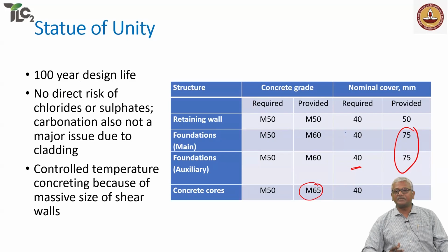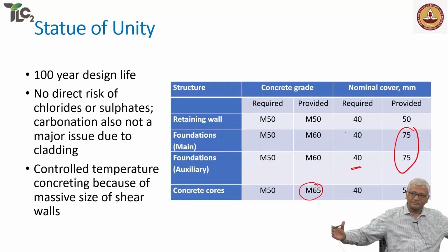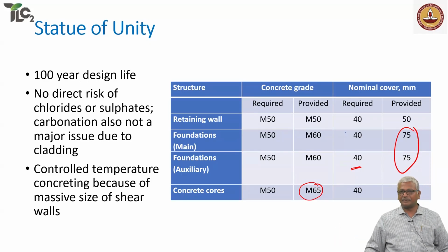Now, imagine having 450 kilogram cement in your concrete, which is massive, and still ensuring that you're avoiding cracking due to thermal effects. And that was a huge problem in this construction project. To avoid cracking, they had to look at possibilities of using extenders and ensuring that they make the strength criteria, but at the same time also ensure that the cracking can be avoided because of thermal effects. Okay, so these kinds of things need to be paid attention to.